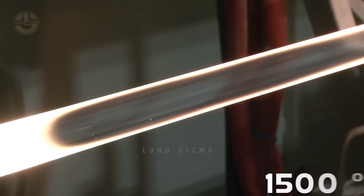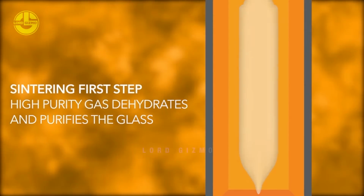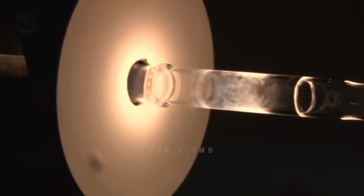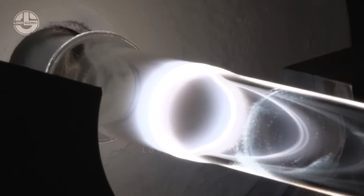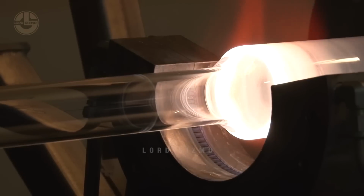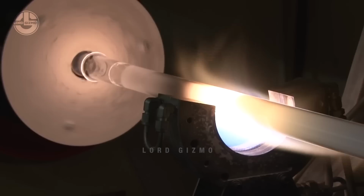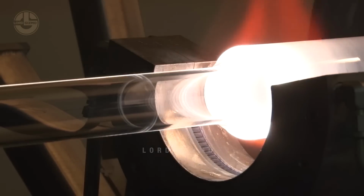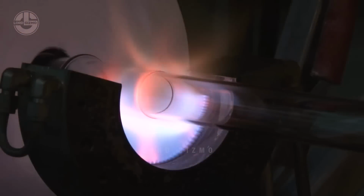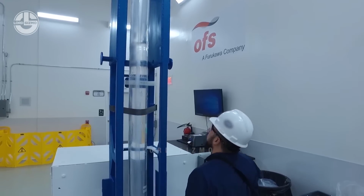At the same time, ultra-pure chemicals are put into the preform, which, when heated and in contact with the glass walls, turn into microscopic particles known as soot. These soot particles begin to adhere to the interior walls of the tube, generating a thin film. Layer by layer, the process continues. This inner layer later becomes the core of the optical fiber. After these layers are deposited, the temperature is increased and the feed of the chemicals is reduced to produce a solid rod, or preform. Now, the ready preform needs to be analyzed to measure its refractive index.